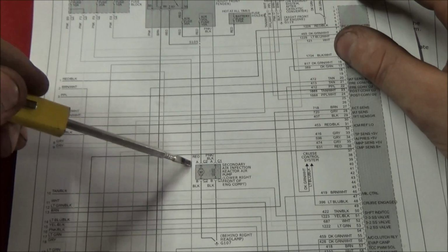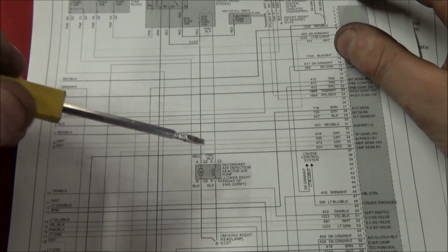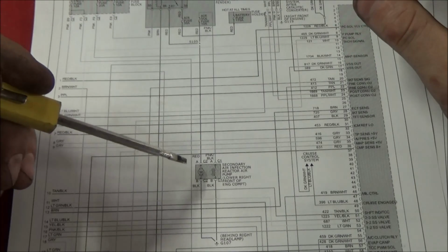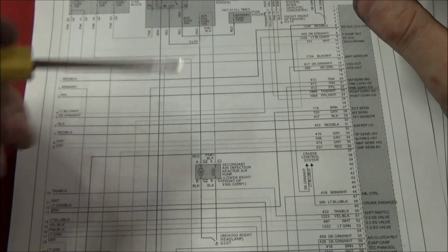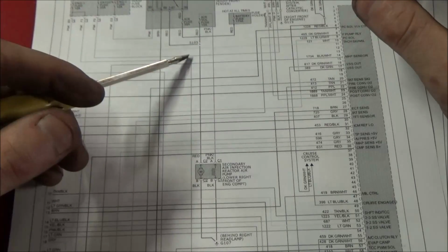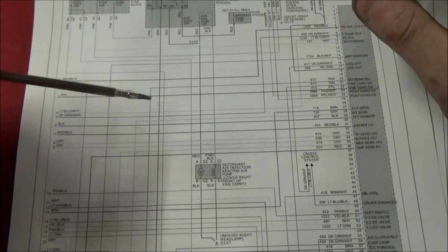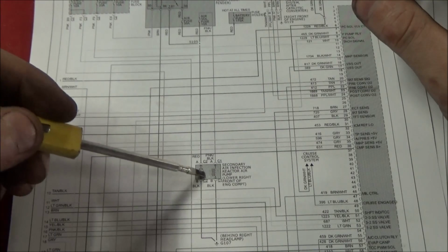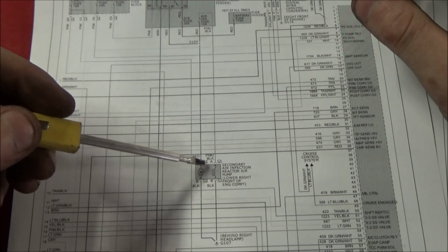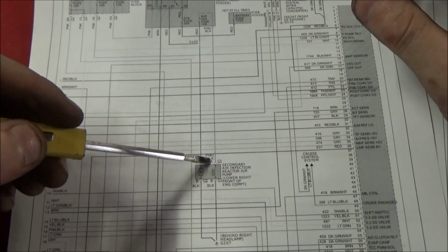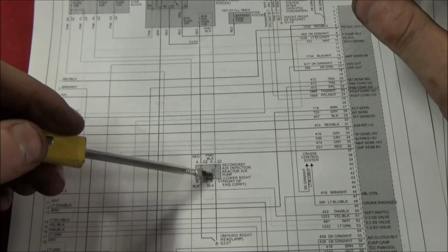So one thing we can use for direction purposes is when we were using that functional test, we were hearing a pretty loud click under the hood. And I've got to tell you guys, it seemed a lot louder than what a relay would to me. It sounded like some sort of heavier solenoid energizing. So what I want to do, guys, is find this air pump unit, and redo that functional test and see if this solenoid is in fact being energized.